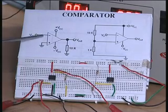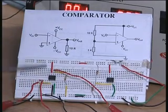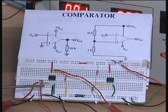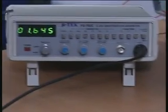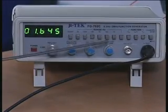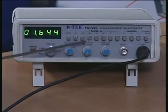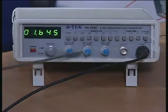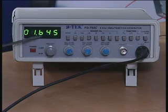Now the same circuit is put here. You can see the operational amplifier with pin 7 connected to plus and the green line, pin 4, connected to ground, and the input is connected to a function generator here, which can generate sine, square, triangle, all those things. It is put in sine mode, and it is around the 10k range. So this is around 1.6 kilohertz.